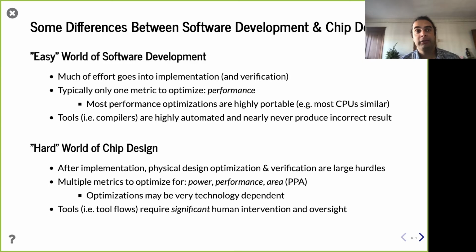One of the classic sources of time is, when you're writing Verilog, you don't know where the delay is, right? You just kind of write hardware and you go with it. But when you start working on optimizing your design, perhaps you're targeting a very high clock rate. To get a very high clock frequency, you need to have a very short critical path. And like I said, when you're writing Verilog, you may not know where that critical path is, right? But then as you start trying to optimize that critical path and make it shorter and shorter, you keep finding in various places you need to keep adding in registers and moving logic around, and that can be a lot of effort, right?